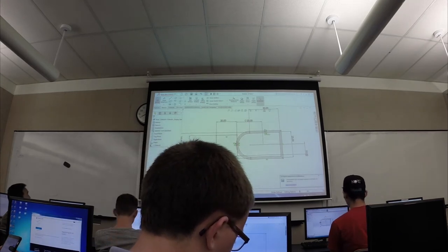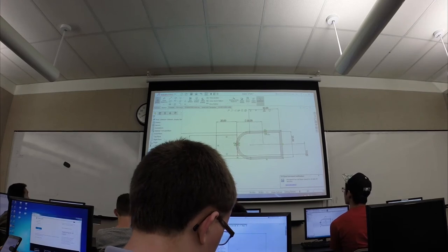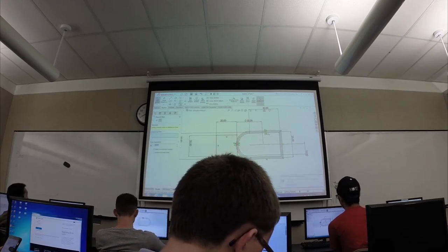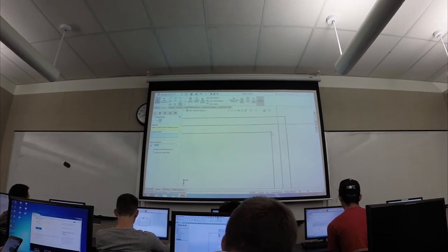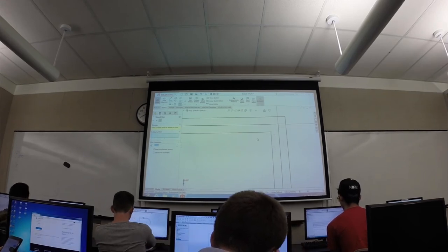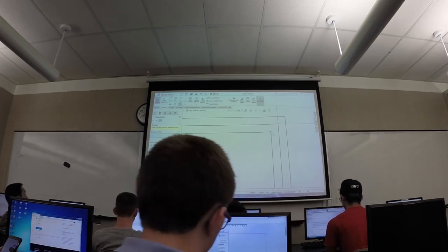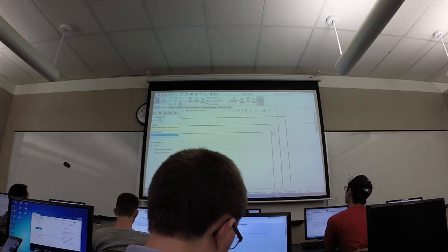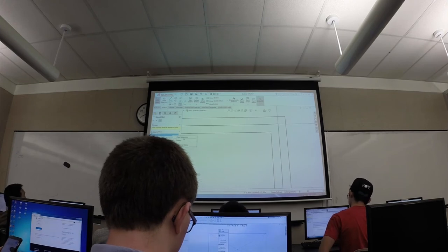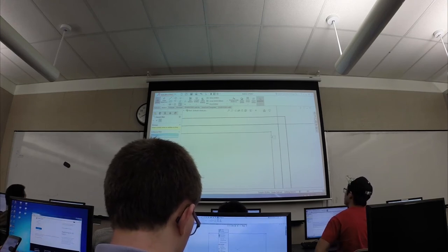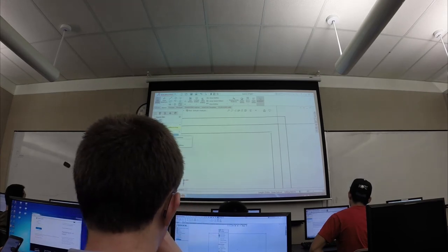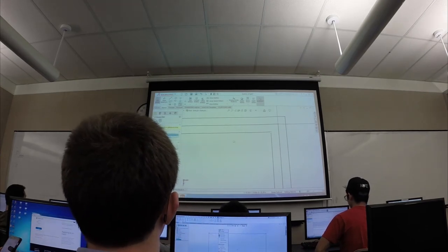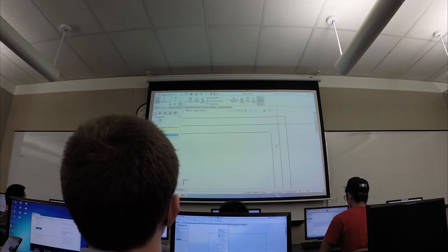And we'll do one for each corner, play around with it. So for now, let's click fillet. We're going to zoom into this corner right here. In order to do a fillet, you could select a corner like that, just a little point, or you could select two lines that would end up meeting at that point. You could select either of those. We're just going to select that point for now, and then we're going to give it a radius of 1 inch.